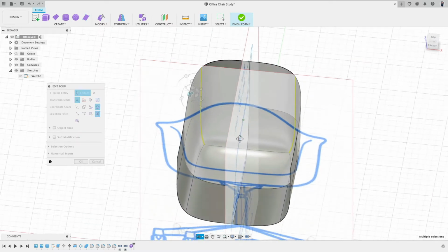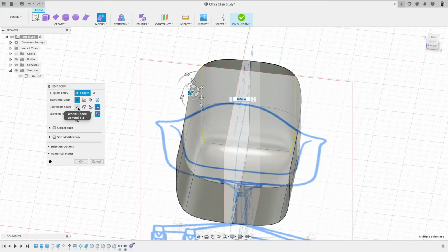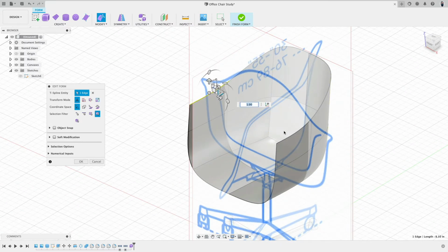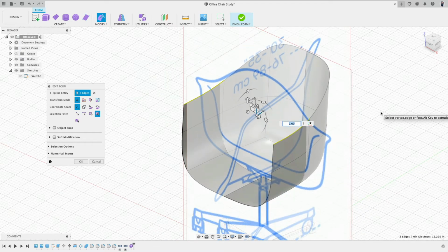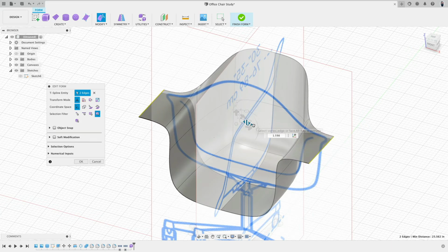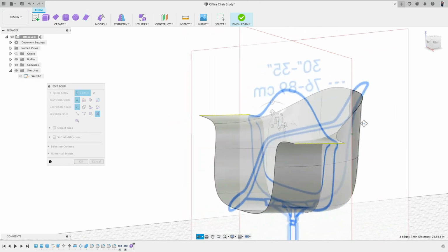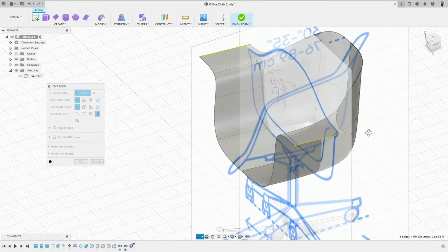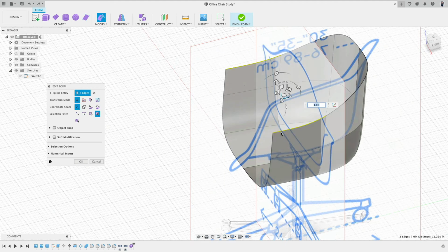We could maybe go back here now to this one, so that the center, I scale those maybe a tick together. And I don't know yet, but when I select these two and then hold the Alt key and click on this scale command, you see how it extrudes and scales an element out, kind of like an armrest. That is actually pretty cool.